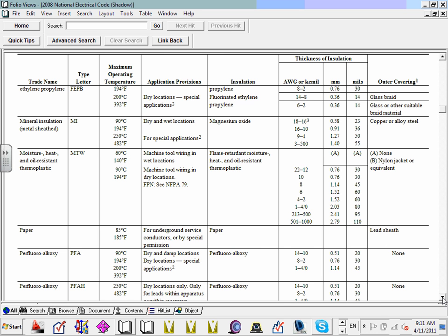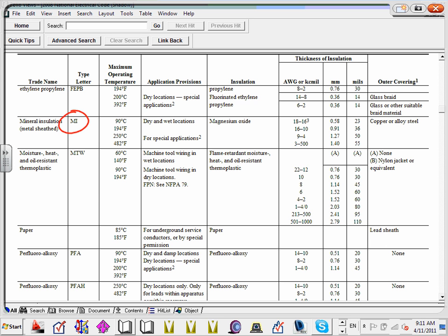On my conduit, guys, if you look at my cable here, mineral insulated, this is a very common wire for fire pumps. If you have a fire pump and you want to wire it for the fire integrity of that cable, this cable would be your favorite insulation. So this table, guys, which is 310.13(A), changed the name.